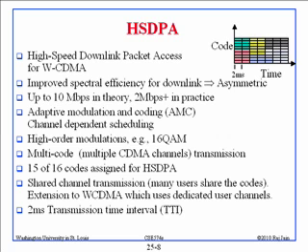And we do adaptive modulation and coding. What that means is channel-dependent coding. Basically, if the channel is good, we use 64 QAM. If the channel is not good, we use QPSK. Right? So that, by the way, was not the case before HSDPA. If you go to 3G or 2G, the coding is fixed.